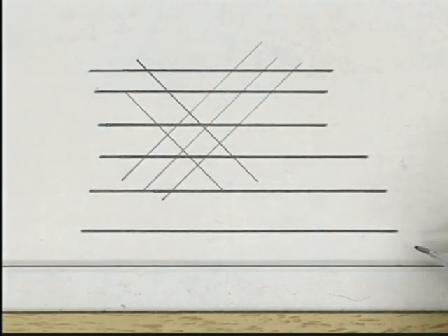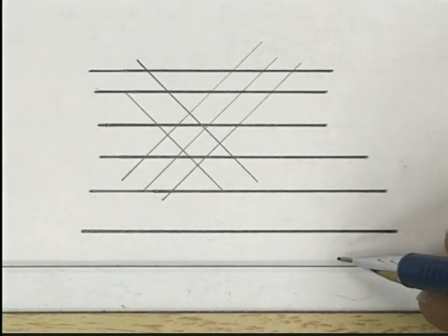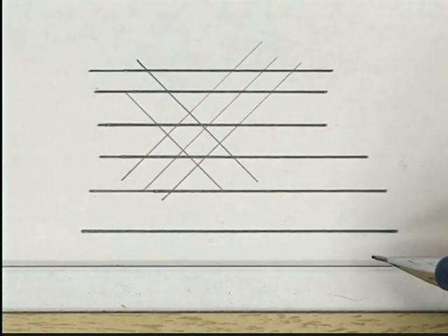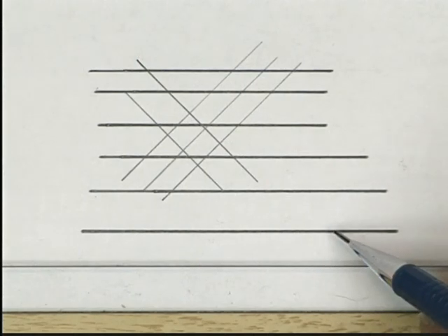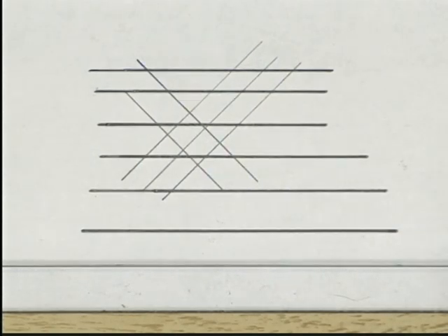Here's something that you might not realize until you get some experience, and that is, no matter how nice a drawing you make, no one will ever look at it. That seems silly at first, but what they will look at is a copy of your drawing. And unless you make nice dark lines with a lot of graphite on the paper, the lines will not make good copies and you'll be a failure. So always make nice dark lines when you're making your object lines.